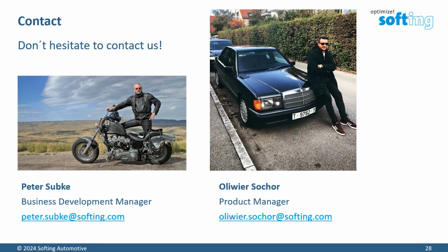The relative adoption of DoIP versus CAN. We talk about DoIP on the DLC, meaning that this is the diagnostic entry point to the vehicle. And CAN is not only high-speed CAN as we had it in the past. CAN is CAN CC, the old school CAN, 1 megabit per second. The other one is CAN FD. And the third one is CAN XL.